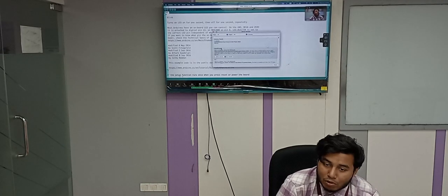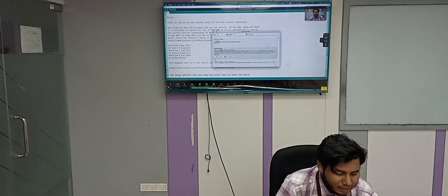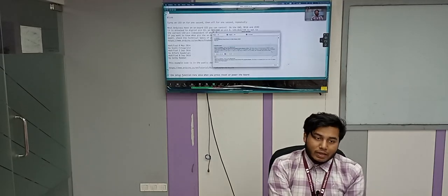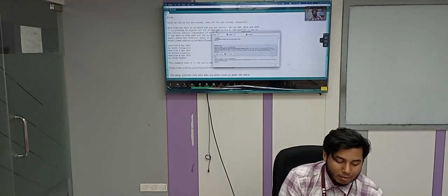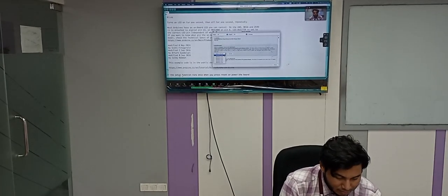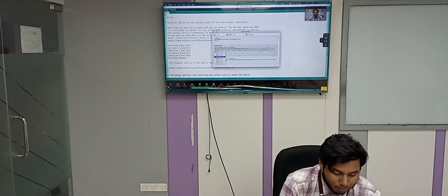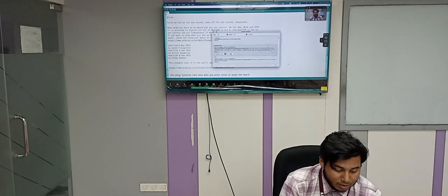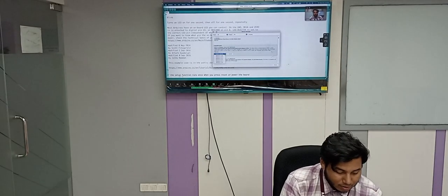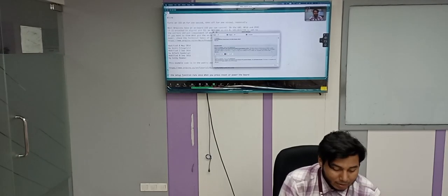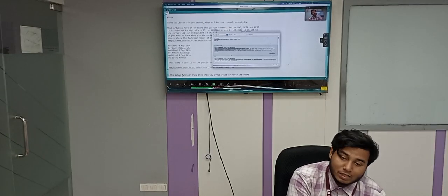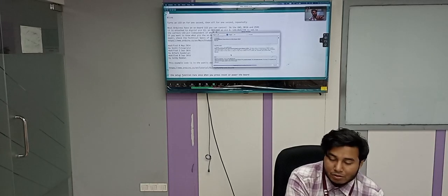See, Liquid Crystal is the most user friendly and most accepted library all over the world. When you're going to work on the LCD display, the Liquid Crystal library is the must-choose library. Here are some selectable versions, like 1.0, 1.0.1 and 1.0.6. See, it's not installed on your PC. If it is already installed on your PC or laptop, then this install button will not appear. Then you select the latest version of the library and install it, so it will install into your PC where the software has been set.